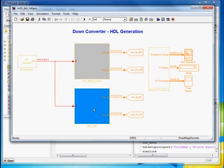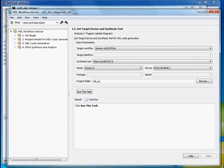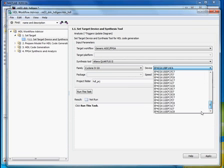And the way we can do that is to launch the HDL Workflow Advisor. And what the HDL Workflow Advisor does is it organizes and sequences all the tasks involved in HDL code generation. So you can see it includes, at the top level, setting the target device, doing some work to prepare the model for code generation, the code generation itself, and then the downstream implementation flow with Quartus 2. So we'll start off by setting the target. We'll go ahead and switch this over to a Stratix IV GX part. We'll choose one of the larger ones there, and then we'll go ahead and run this task.